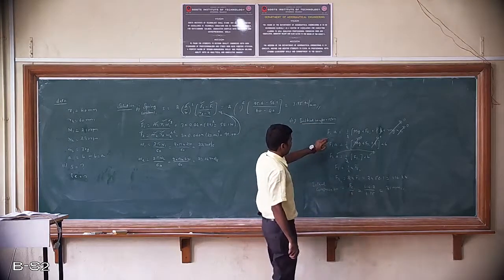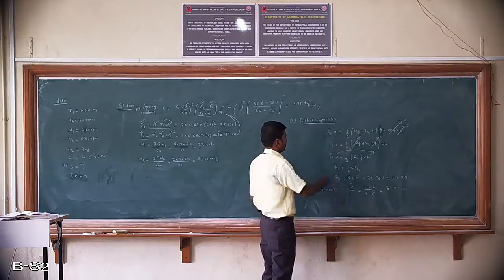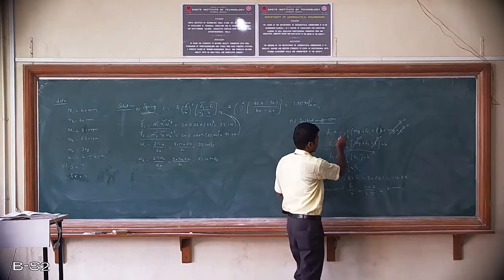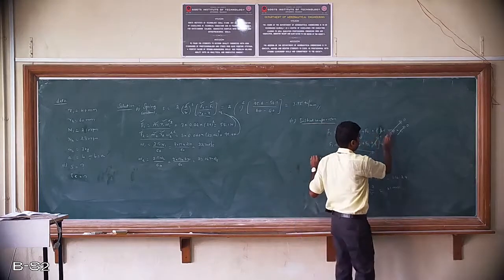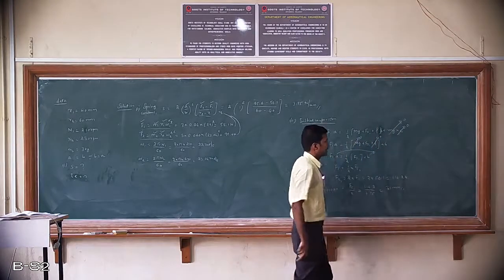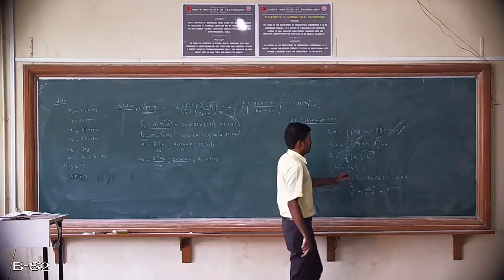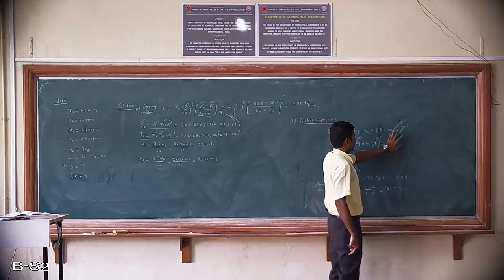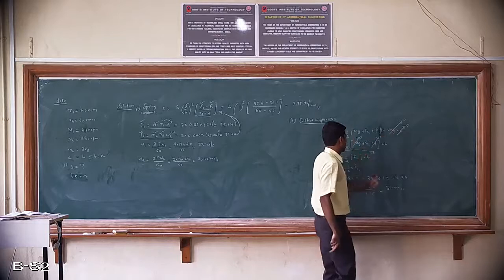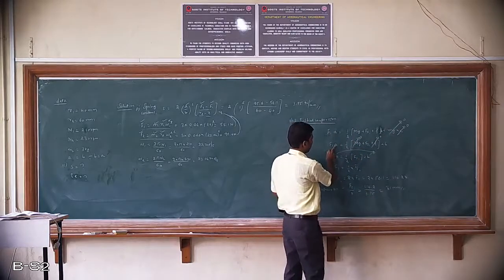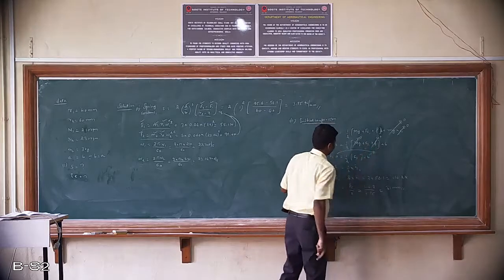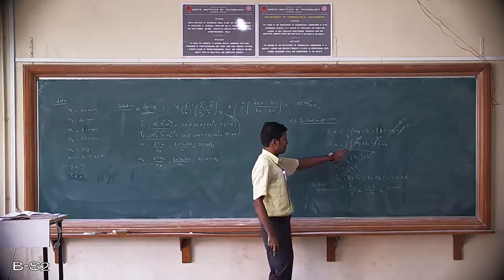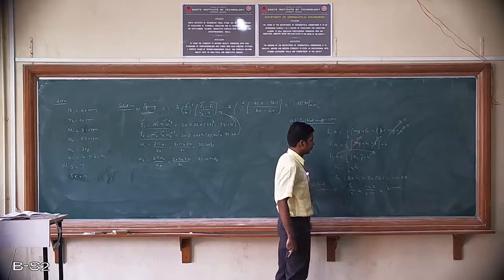To get the value of Fs1, I will use the equation F1 into A is equal to 1 by 2 into mg plus Fs1 plus F into B plus mg into C1. By neglecting the obliquity of the arms, C1 multiplied with m into g becomes 0. The remaining term is F1 into A is equal to 1 by 2 into mg plus Fs1 plus F into B. In this problem, the mass of sleeve is not given, so I will take it as 0.